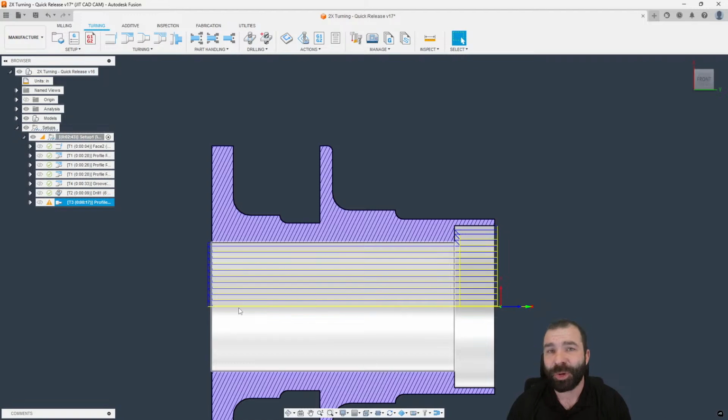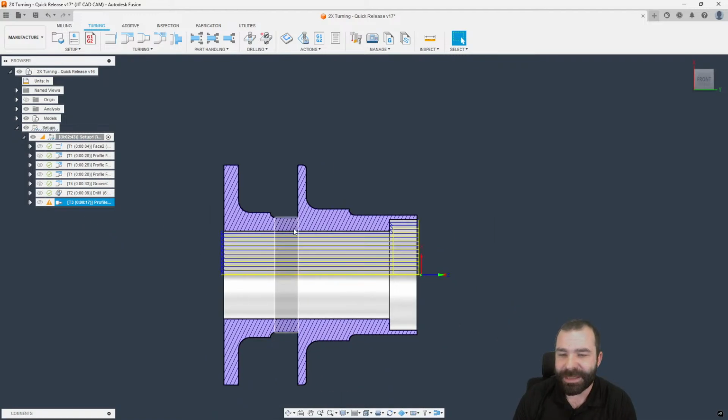The secret to creating any toolpath in Fusion all relies on one: get a path on your part. Even when I do 5-axis machining, I do a 3-axis toolpath, then convert it to 5-axis, so I can at least see where those blue lines are. Now, for those of you that don't know, when you're doing turning, obviously we've pre-drilled this. We never want to start on center. So again, we need to think, do I want my blue lines to stay in the Z area that it's working? In this case, yes. So I need to change my X and how my X is affected.